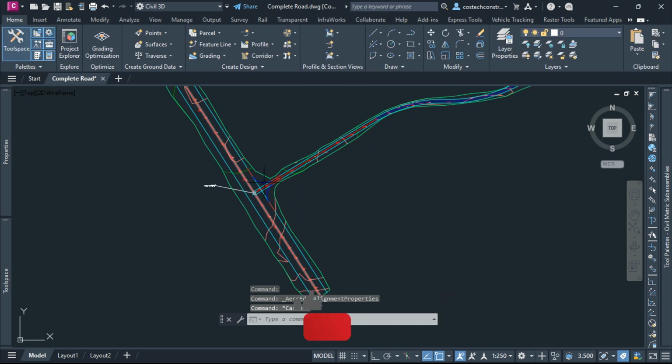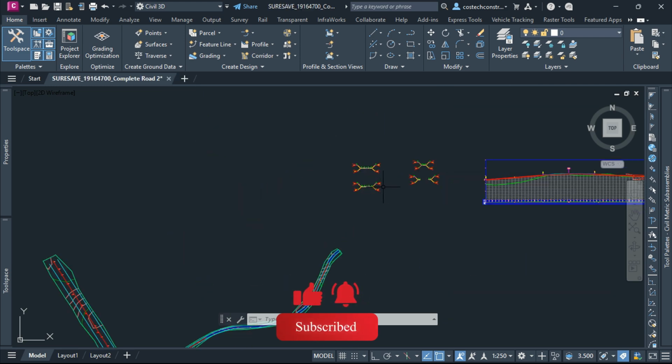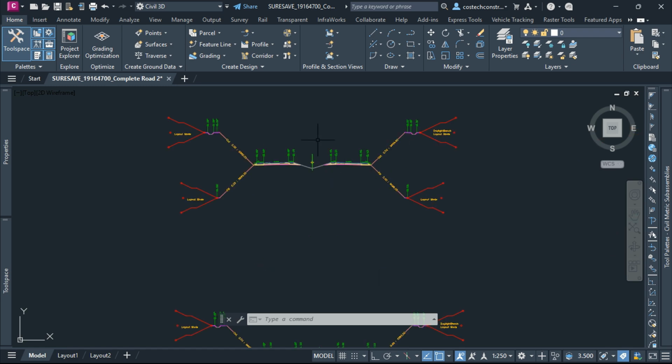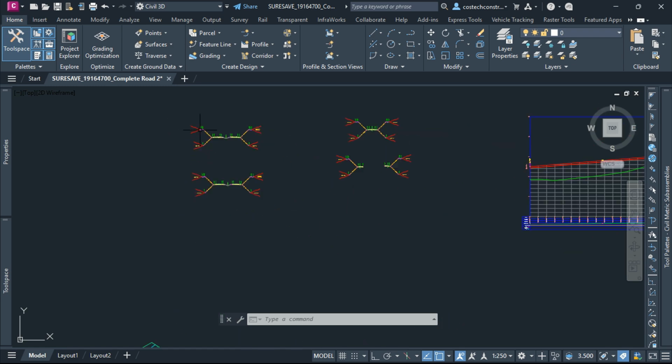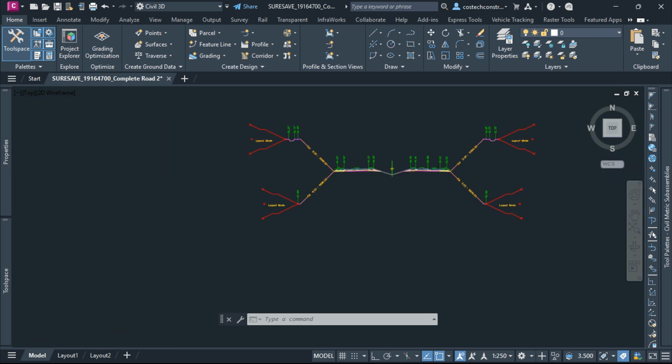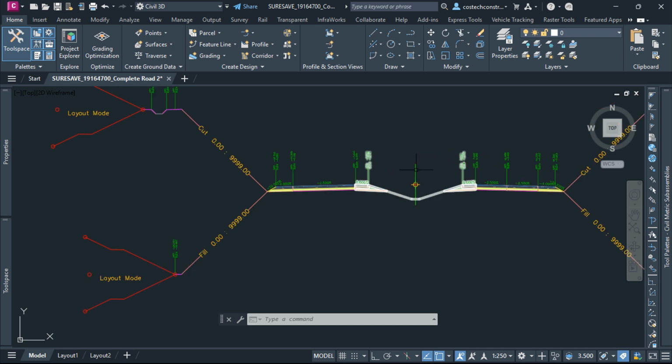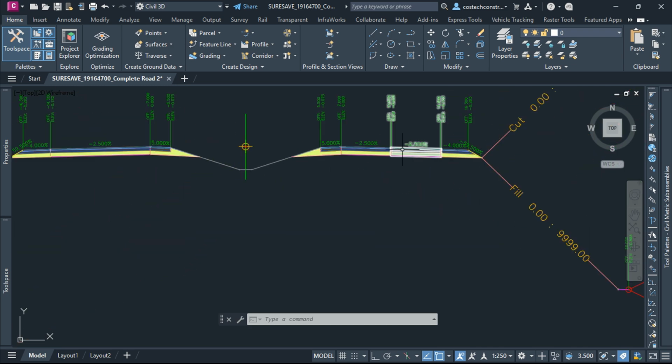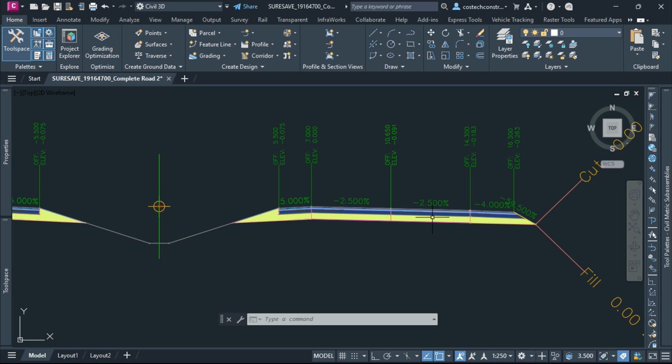We now have all the required assemblies for our corridor modeling, which will be the next video after this. I will briefly explain a crucial detail before ending this video using this assembly. The right side contains assembly details for a divided crown road type. This lane, which is closer to the median, is defined as the right inner lane and this other the right outer lane.